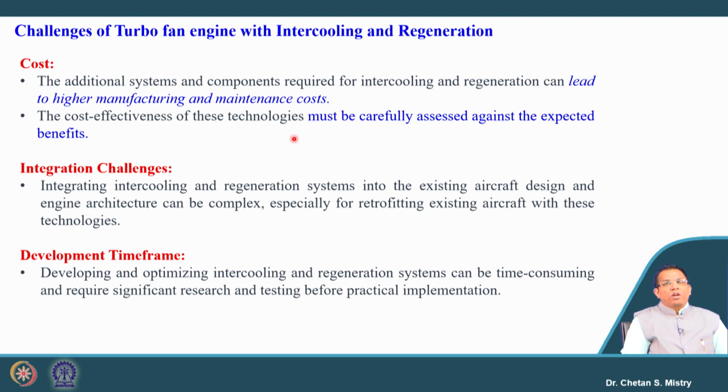So overall, if we look at this configuration, intercooling and regenerator are more promising for the land based power plant. But when we talk about application for aero engines, where we have a lot of constraints in terms of size, weight, operation, safety and certification, there is a long way to go.